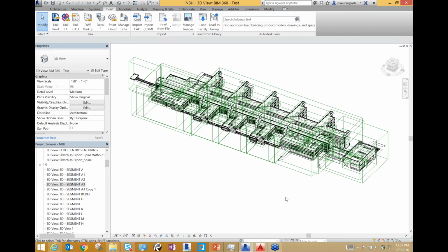It did not make sense to build the model all together at once. So what we helped this company do is limit the view of their model. We broke their model up. So how did we do that? By limiting the view. Well, there's two ways that we've done it. The first one that I'm going to talk about is really our best practice. And what I suggest is designing or building your model by your floor plan.